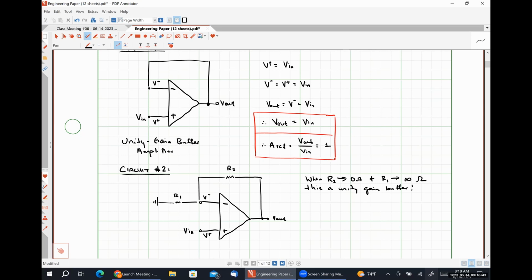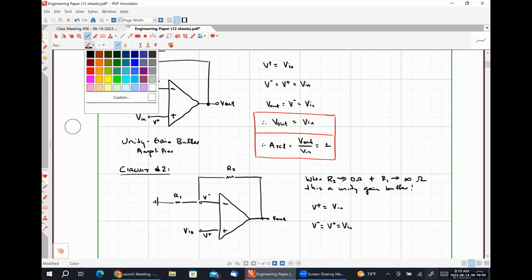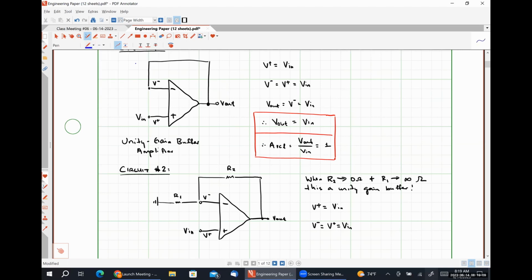So for our analysis here, we're going to find out what our voltage is at the non-inverting input terminal. Obviously, we just have Vn by convention once again, which means the voltage present at our inverting input terminal is also Vn. And what we're going to do now is apply Kirchhoff's current law at the inverting input node. So I'm going to add this current plus this current together.